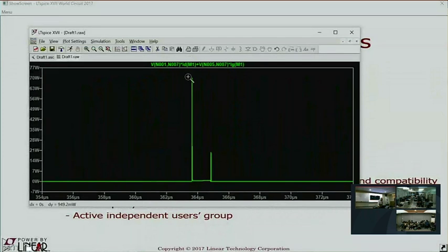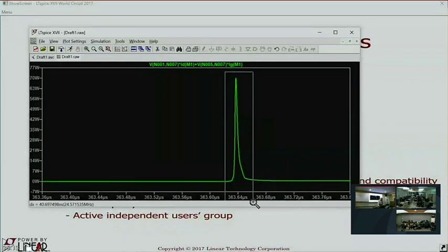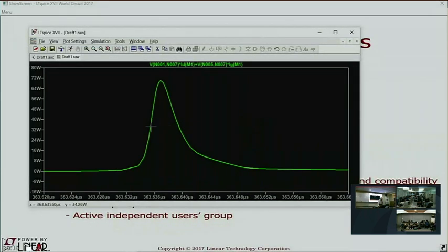Let's zoom up on this thing. What we want to do is measure the width of these pulses. You can set up attached cursors and slide them around, and it'll read out a difference. But there's a much easier and quicker way of doing it. Let's say I just pretend I'm going to zoom into this region, and when I'm dragging this box around, down here the size of the box is read out.